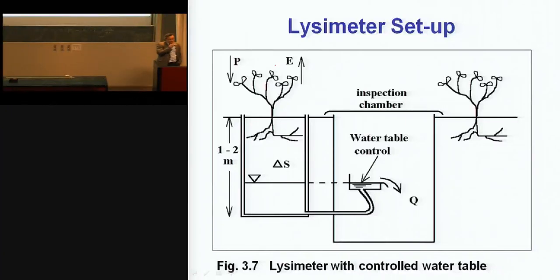Before the coffee break, we discussed the dirty evaporation pan. I hope I didn't say something wrong. When the water is dirty, it's darker, so more absorption of energy instead of reflection. Therefore, more heating up of the water, more energy available to evaporate. So you have more evaporation probably out of a dirty water compared to a crystal clear water.